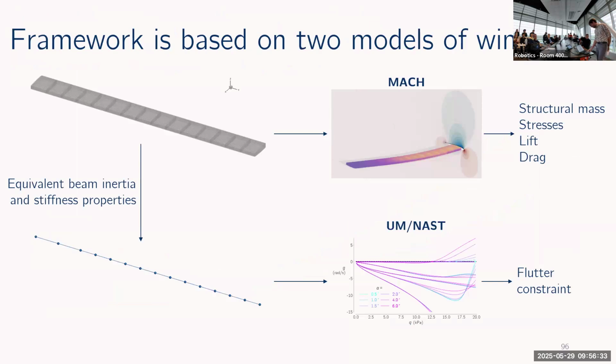Yeah. So on your first question, if I was designing a real aircraft, how would I do it? I think I would go to something kind of similar to this flutter constraint framework that I had, because one of the big problems in all of our optimization problems is that because we use such expensive models, we can only consider a handful of flight points. But in reality, you have to size a wing structure based on literally on the order of 1 million different load cases.